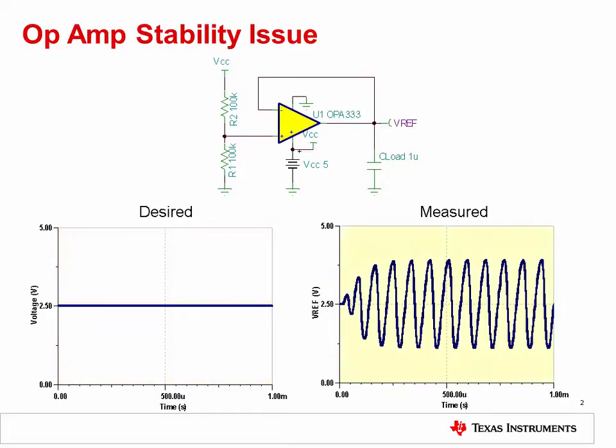However, the unstable design resulted in a sustained output oscillation, which has turned the DC reference voltage into a sine wave. Even though this circuit is meant to operate with a DC input and output, transient disturbances on the input, power supplies, or on the output may cause the amplifier to begin to oscillate. Therefore, we recommend checking every op-amp circuit for stability regardless of the closed-loop signal frequency of operation.